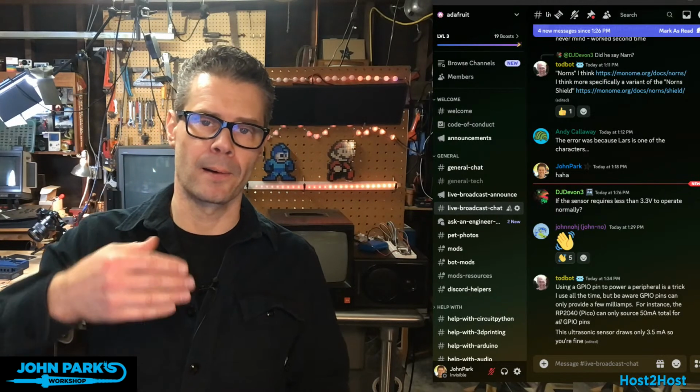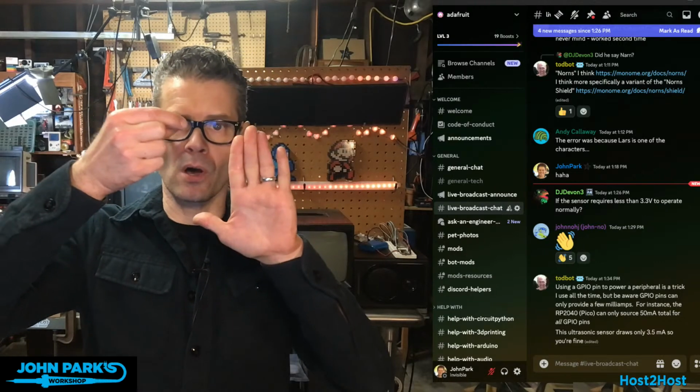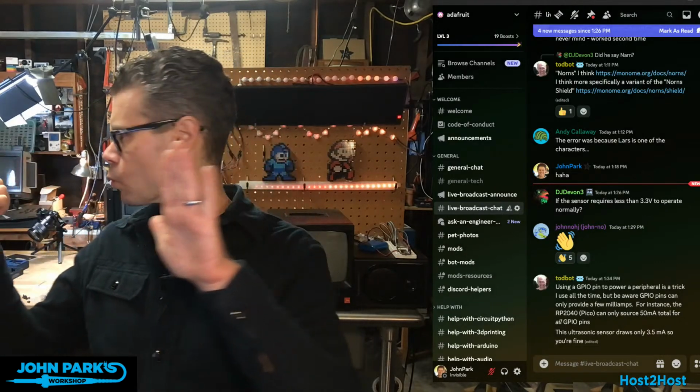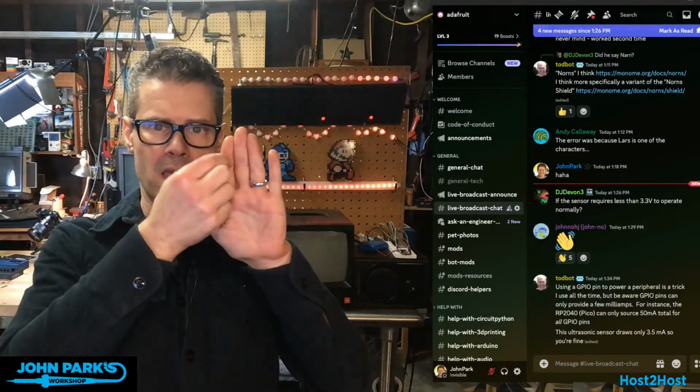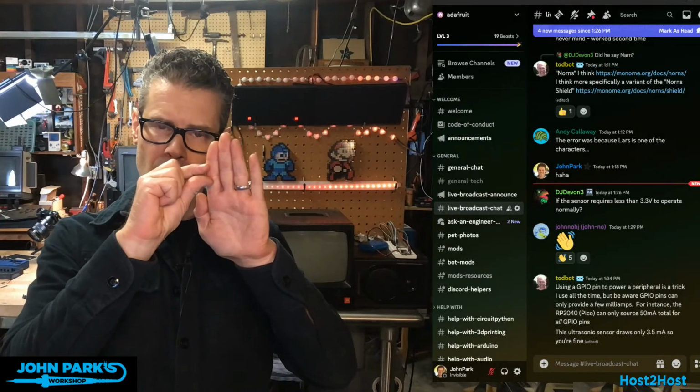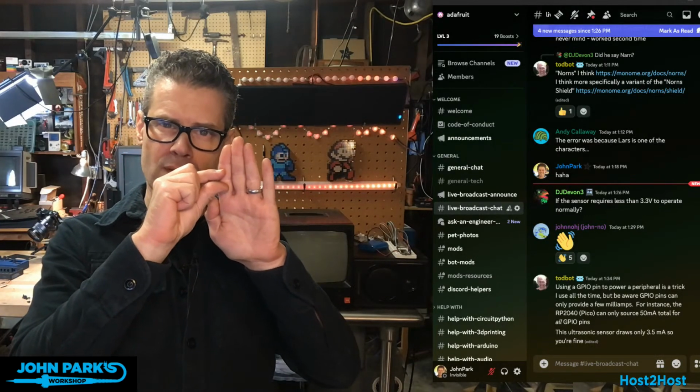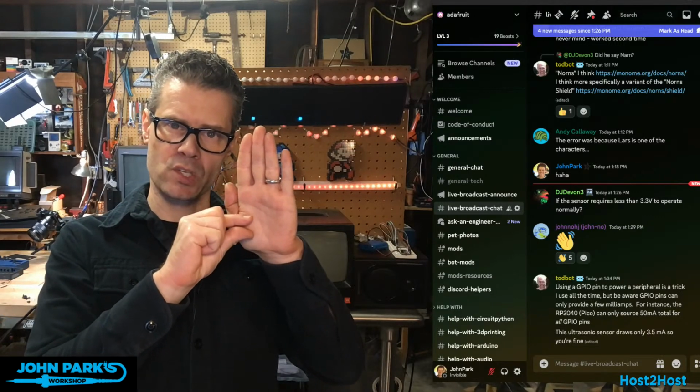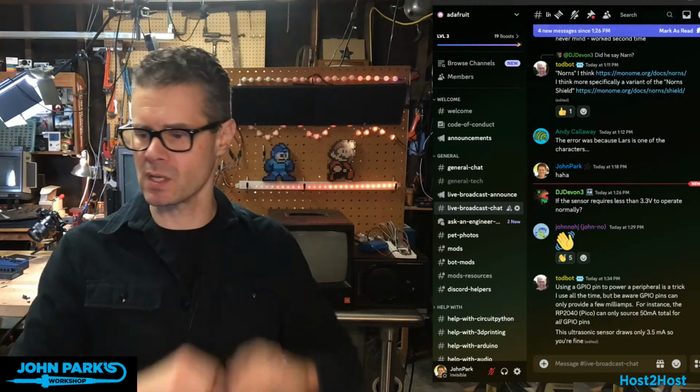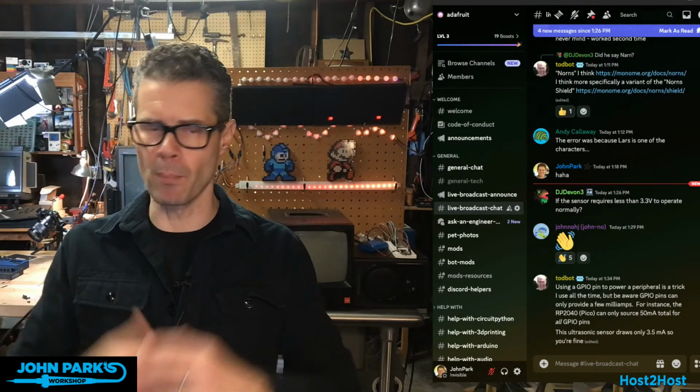A more typical thing is float sensors, with a Hall effect sensor, which is actually what there is inside of my espresso machine tank. There's a little magnet in a piece of foam, and then there's a Hall effect sensor, and that's how it knows when it gets low enough to stop. When it's almost empty, that's how it shuts the pump off so it doesn't draw more water into the boilers. That's one way.